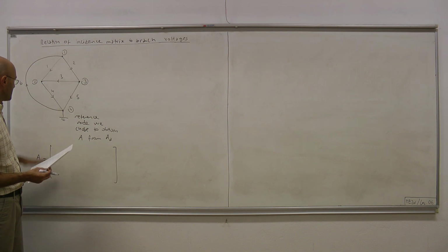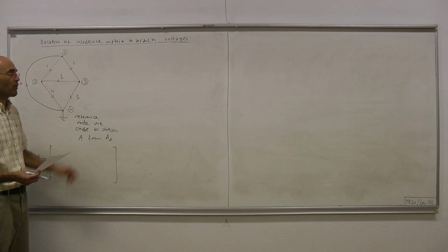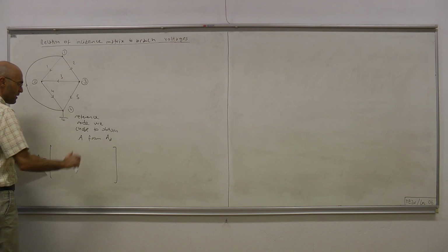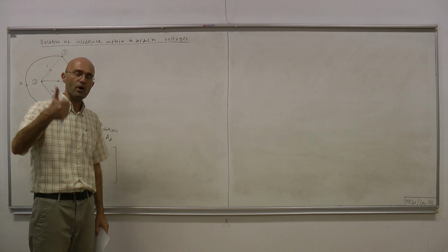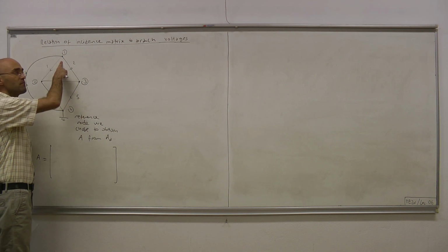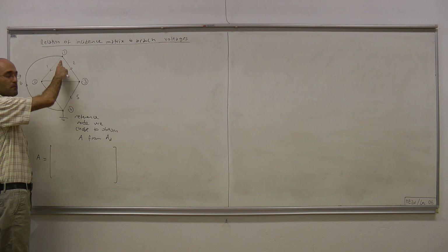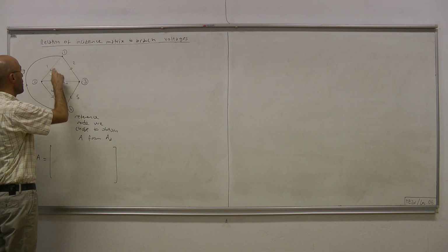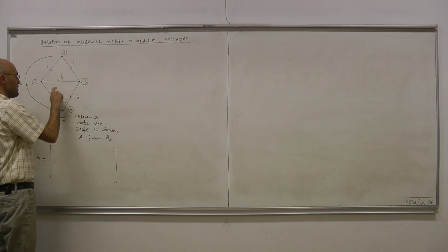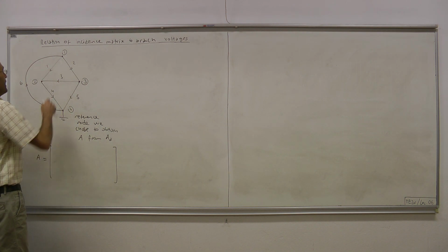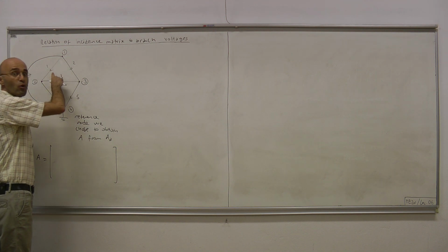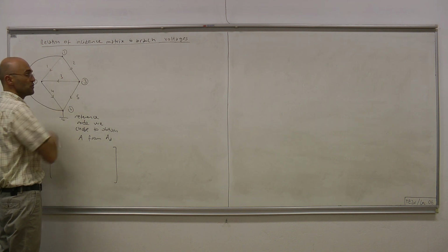For each node there corresponds a row. For the first node we have the first row, and the first row, like all other rows, has entries either 1, -1, or 0. So you look at the corresponding node, let's say the first node. Associated branches are 1, 2, and 6. So that means entries 3, 4, and 5 must be 0. Branches 1 and 2 are outgoing, and 6 is incoming, therefore the entries for 1 and 2 will be +1, and for 6 will be -1.